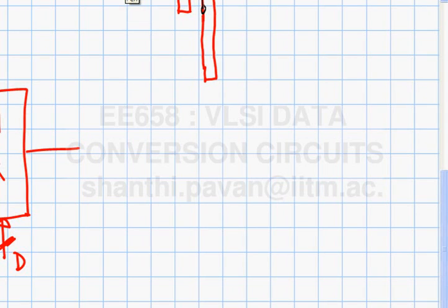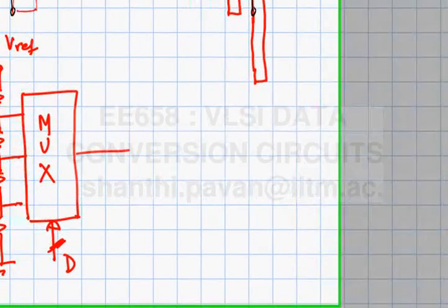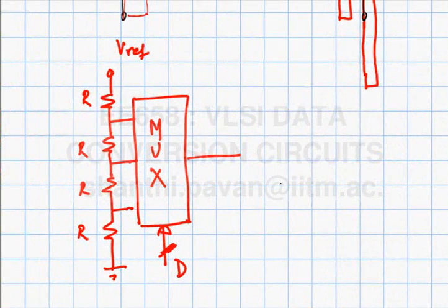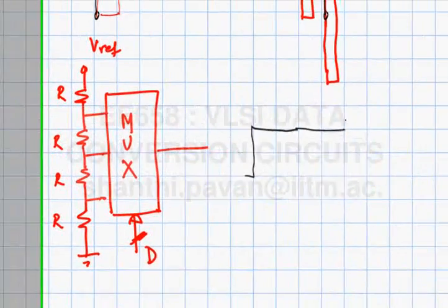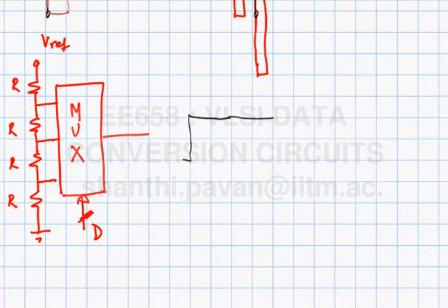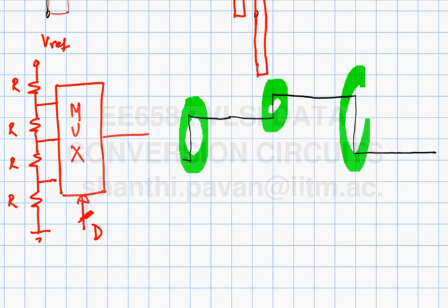See, an ideal NRZ output waveform is supposed to be like this. I'm going to grossly exaggerate the time interval as well. So this is an ideal DAC output waveform. So what can you say about these edges? In an ideal NRZ waveform, they must be infinitely sharp.